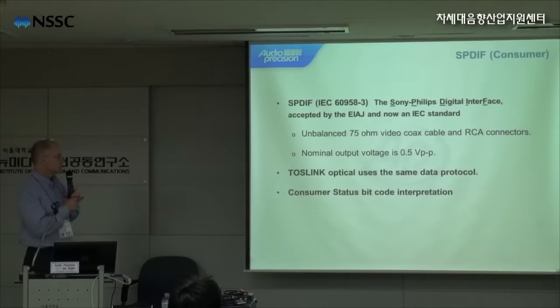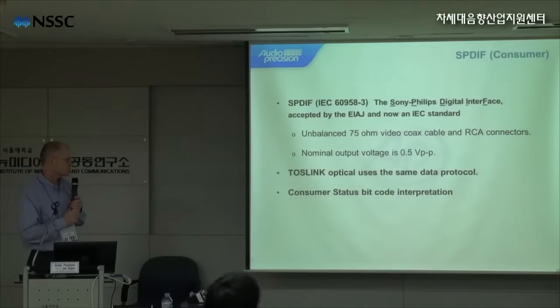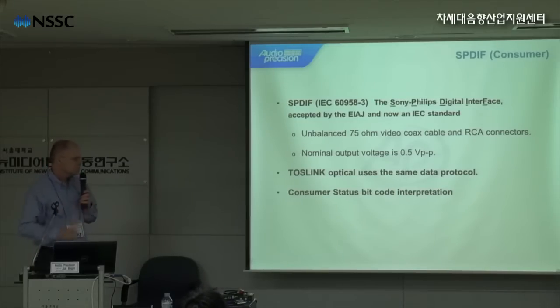Now, SPDIF consumer stands for Sony Philips Digital Interface. It was accepted by the EIAJ, and it's now an international or IEC standard. It uses unbalanced 75 ohm coaxial cable and RCA connections. The nominal output voltage is 0.5 volts peak to peak. The Toslink optical uses the same data protocol, and these two interfaces use what we call the consumer status bit code interpretation.